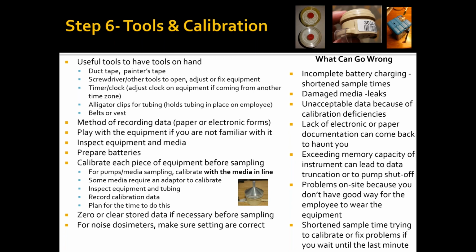Those work great. Just remember that they can get really dirty and maybe you have some decontamination issues you have to think about. A couple of other things is play with the equipment so that you know what it does. Inspect it. Up in the corner there in that middle slide is a PPI sampler that came from a laboratory. You can see that crack running right down it. They came from the lab that way, and obviously that's a leakage problem and is going to create issues.